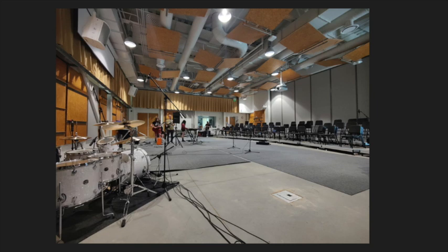About 750 square feet of carpet was acquired based on the parameters of configuration 4 and placed into West Village 175. A recording session was held to demonstrate the differences in reverberation time. Musicians observed a drastic reduction in reverb when curtains, partition, and carpet were all engaged. For speech intelligibility, an RT60 of 1 second is an industry goal, particularly in classrooms where speech occurs. Both through calculations and the above observations, this is now achieved with carpet.